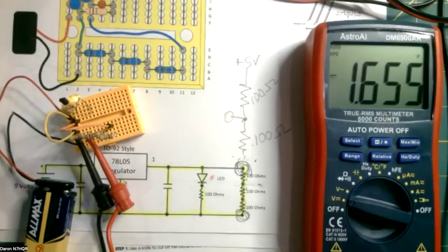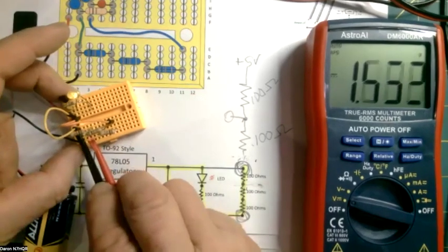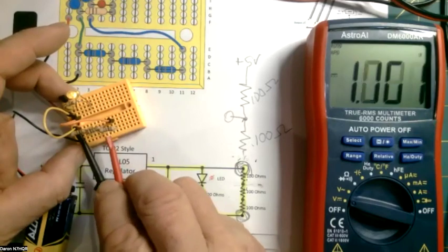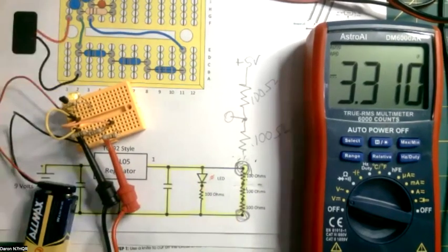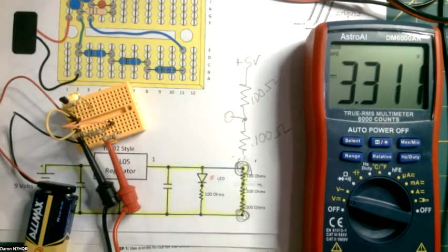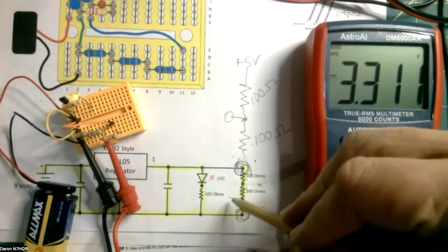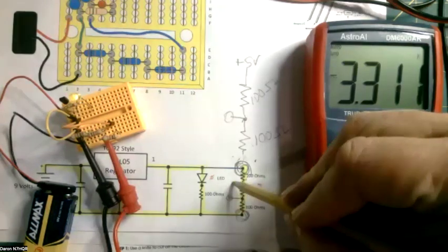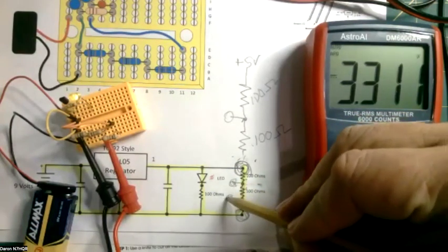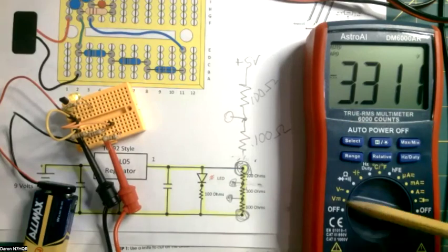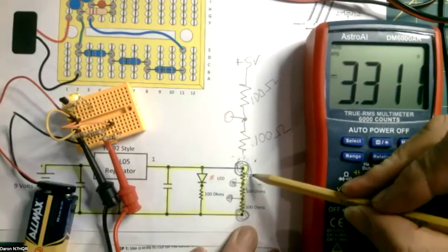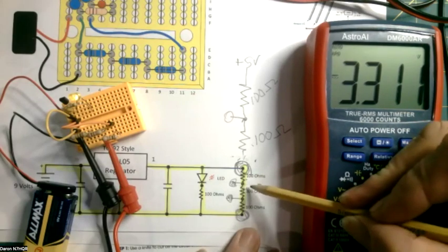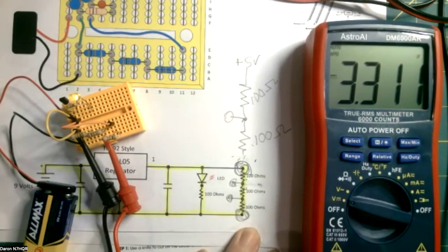Now go to the next one, number 2. Two-thirds of 5 volts. Correct. Two-thirds of 5 volts. That's a voltage divider. So these are the places we were looking on the schematic here. We had 200 ohms on one side and 100 on the other side, so it's not going to be equal. And then we had 200 on the other side and 100 on the original side. So divided into thirds.